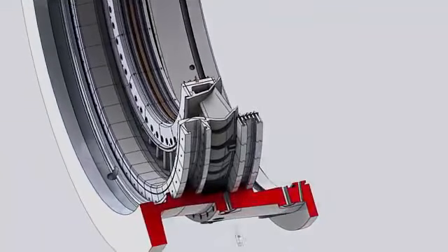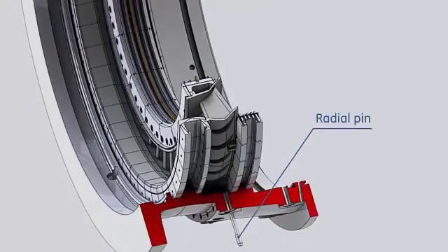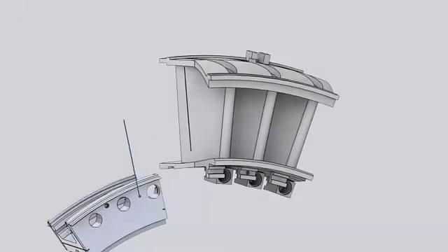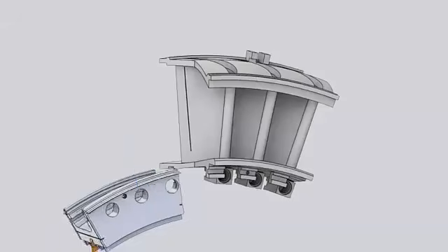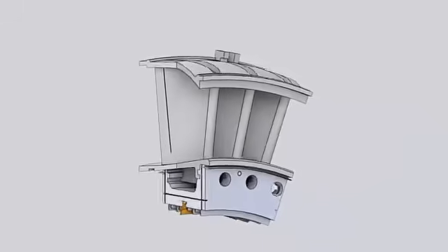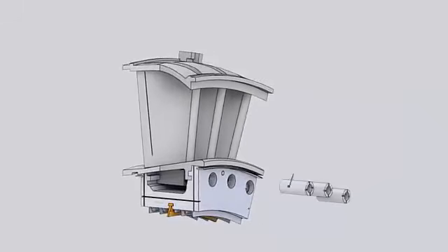The nozzle segments are held on the circumferential position by radial pins from the turbine shell into axial slots on the nozzle outer sidewalls. Annular curved segments are attached to the inner sidewall of the nozzle. These segments are called the diaphragms. Each diaphragm is secured to the nozzle by a pin. These diaphragm segments prevent hot gases leakage past the inner sidewall of the nozzle and the rotor.